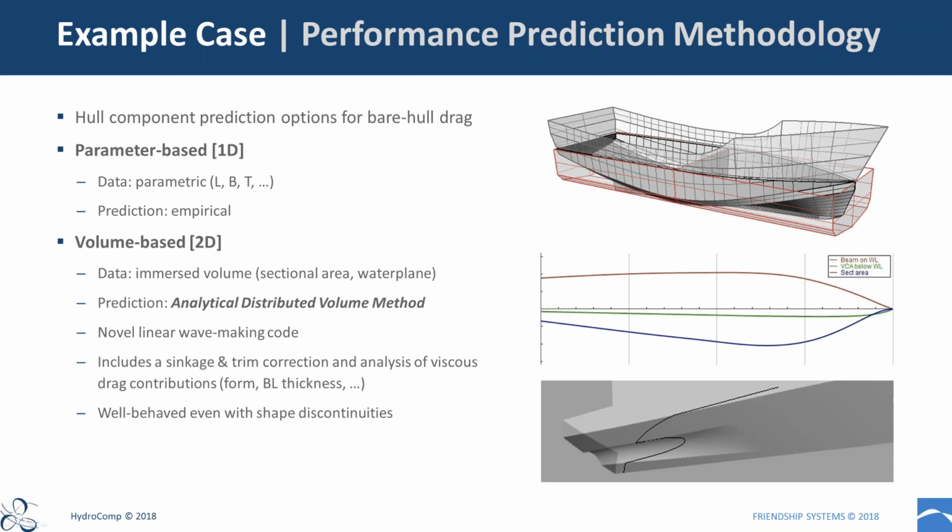So to keep hull geometry as simple as possible, I think it's important to have an objective in setting up the CAD geometry for optimization studies: that you look for a set of parameters or a parent shape that is really CAD friendly and morphing friendly, that you don't over constrain it, and that you use the understanding of the physics of hydrodynamics to reflect some of those things that we know are going to have an influence: transom immersion, longitudinal center of buoyancy, the fineness of the nose.